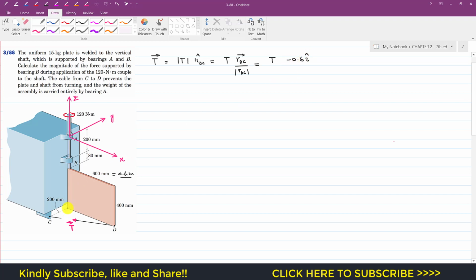Once we reach here, we have to travel this distance in the negative y direction. This is our positive y, so we have to travel 200 mm. 200 mm divided by 1000 gives 0.2 meters. So we travel 0.2 meters in the negative y. I will write minus 0.2 in the negative j. So this is the position vector from D to C, and now we have to find its magnitude.